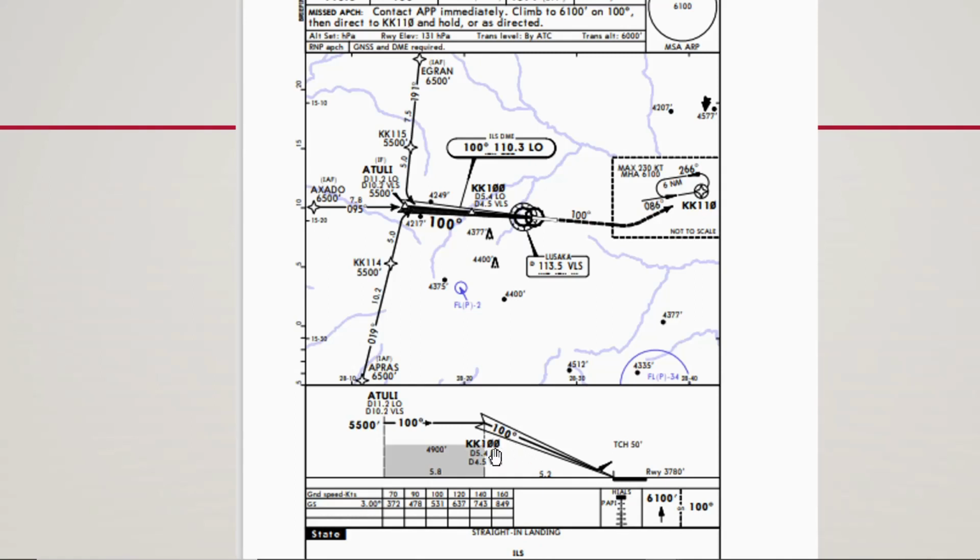This is the Lima Oscar, an NDB. This point here is 5.4 miles from Lima Oscar and 4.5 miles from the VOR, which is Victor Lima Sierra. So we will tune in Victor Lima Sierra once we set the aircraft exactly to intercept this point, and you will see on the DME it will be 4.5 or somewhere around there, and then you will see the aircraft will exactly intercept at the proper point for it to go down.